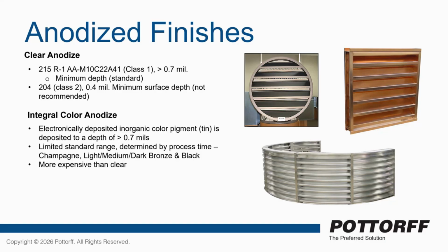From what I've been told, with the anodizing process the darker colors are going to look better than any of the lighter colors. So your champagne is going to be the lightest color that you can have, all the way up to a black. And from what I've understood, the black might hold its color better than some of the champagne. But again, it can have a great weather resistance for holding up that anodized finish. So a good longevity on these types of applications in your field.